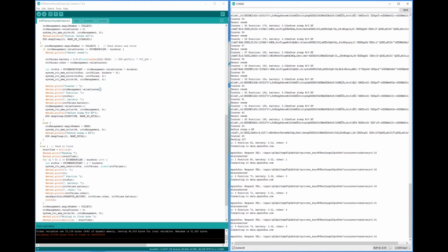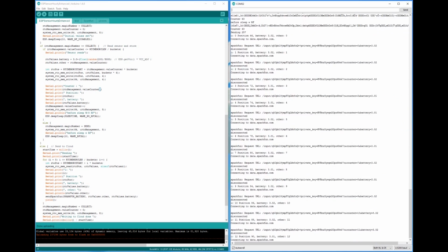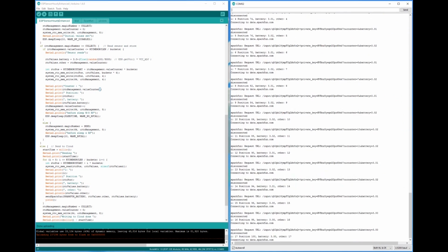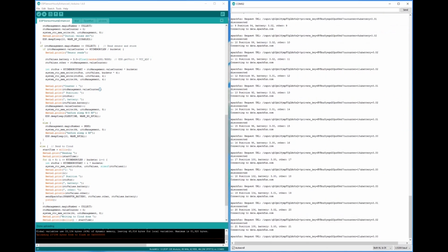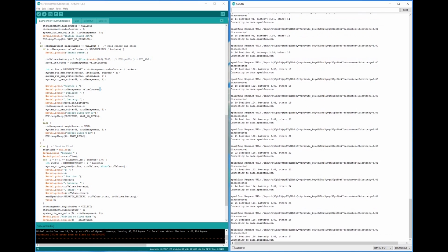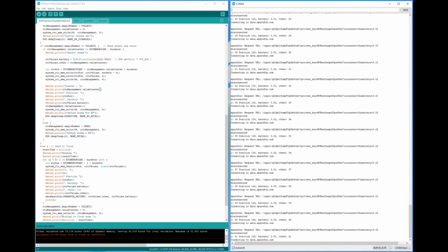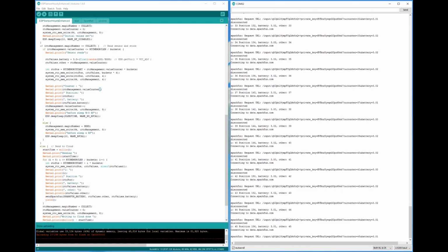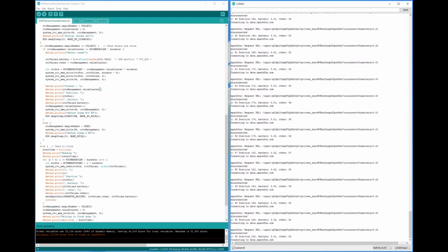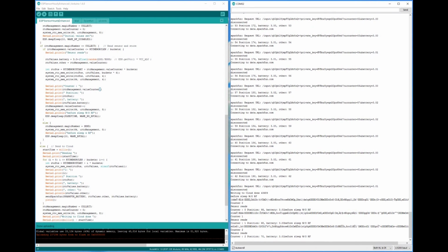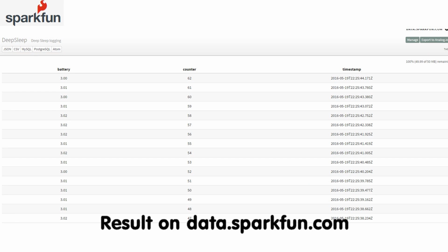SparkFun's reaction time was quite slow. On average it took about 3.5 seconds per line of transmission. The fastest postings, however, were well below a second. In video number 58, the transmission of one value took us about 8 seconds. So, with a fast cloud service with response times below 1 second, we can reduce the power-intensive phase by a factor of 10. So, our sensor will run again much